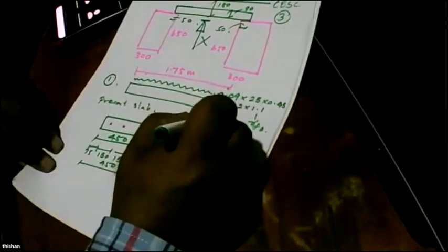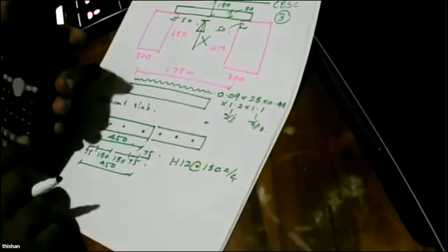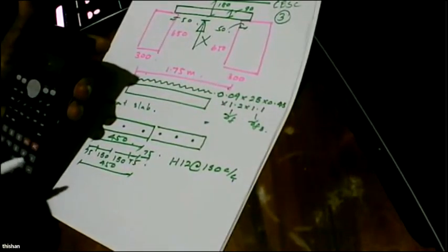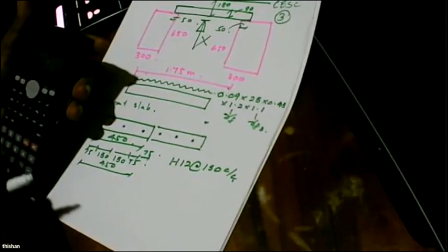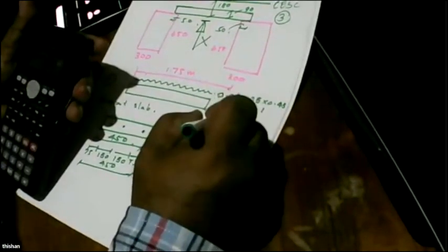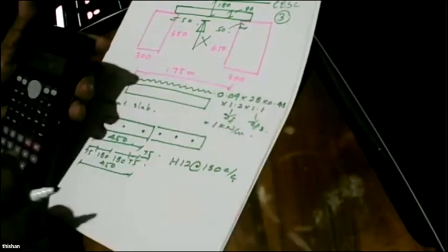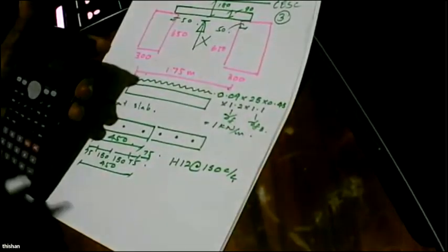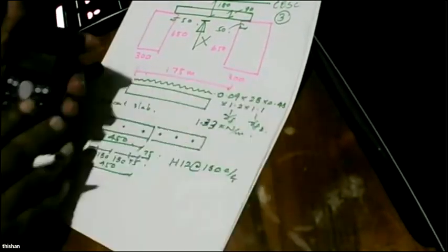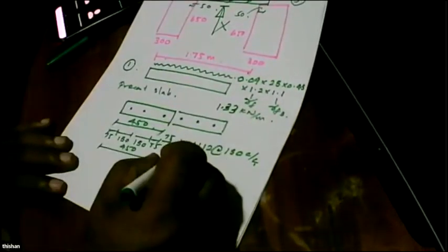With this, you can find the loading intensity, which is 0.09, because of the 90 millimeter thickness, multiplied by 0.45, that is the width, multiplied by 25, will give you something like 1 kilonewton per meter. Multiplied by 1.2, multiplied by 1.1, that gives about 1.33 kilonewtons per meter.